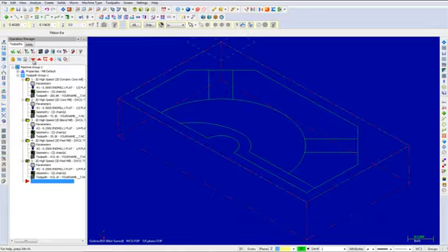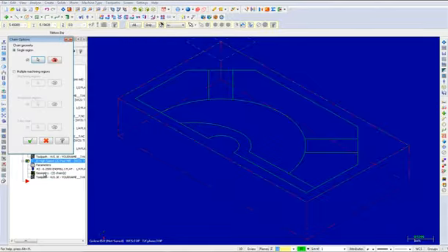We will now rechain the geometry. In the operation number 5, pick Geometry. From the chain options, click on the Unselect button to remove the existing chains. Now click on the Select button.